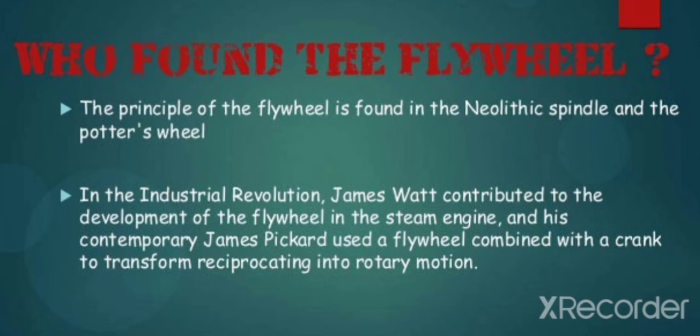What is basic difference between flywheel and governor, which we have seen in earlier lecture? As we all know, the energy stored in flywheel is kinetic, which is 100% available, but in governor friction is involved. Okay, in governor friction is involved. As we all know, if we have constant load, then governor will remain ideal, but due to cyclic fluctuations in energy, flywheel will always work. Okay, governor has no influence in cyclic fluctuations in energy, whereas this flywheel has no influence on mean speed of engine. When the engine speed is at mean, this flywheel has no influence, whereas when there are cyclic fluctuations in energy, governor will have no influence.